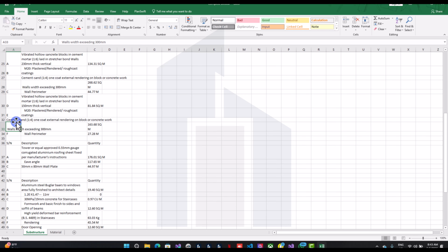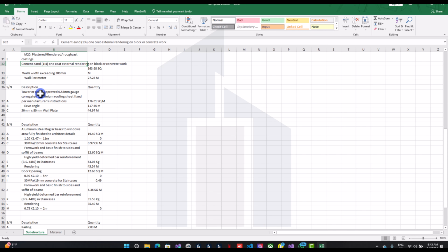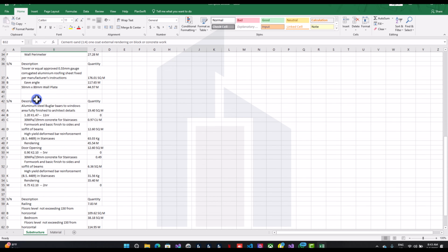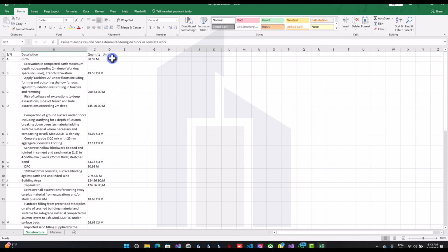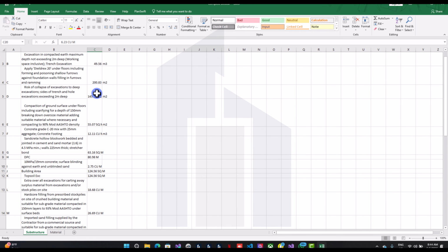So if you have a bill format, you can either make use of the existing bill format you have prepared, or you'd just use this to create your bill format and use it like that. Okay, so units, meter cube, meter square. So you can just have this here, then take this out. So this is you using the exact quantities, and you have your bill preparation done. So this is basically just you doing more of some manual adjustments.